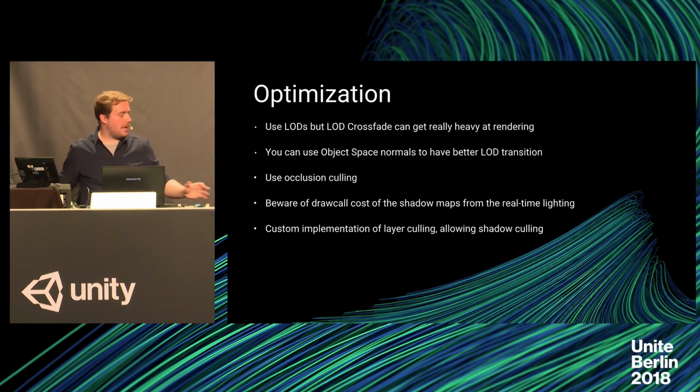But for us, I had to see how much I could improve the scene on the content side. So of course, you need to use LODs. There is no way around it. But you have this checkbox in the LODs that is LOD crossfade, and it's really nice and really tempting because it makes the transition between the LODs a lot better. It will smoothly crossfade from one to the other. It's really nice, but we realized how heavy it was. It is going to increase the amount of draw calls in your project.